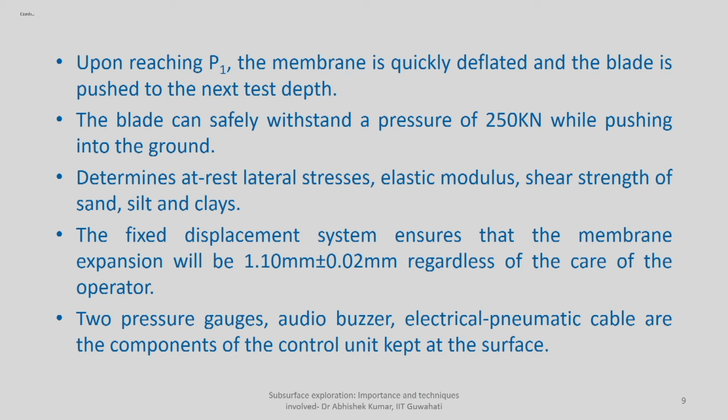Every time you do the test, it keeps giving you two values, P0 and P1. Of course, you have to apply certain corrections, which we will discuss at a later stage. Now, whatever blade you are using, you are pushing it into the soil, so the blade itself should be strong enough. It should withstand a pressure of 250 kilonewton while pushing it into the ground.